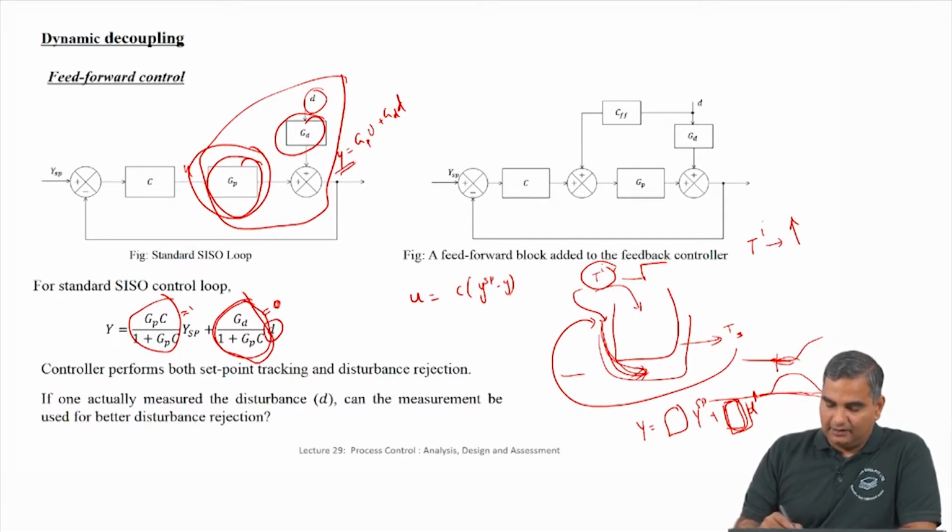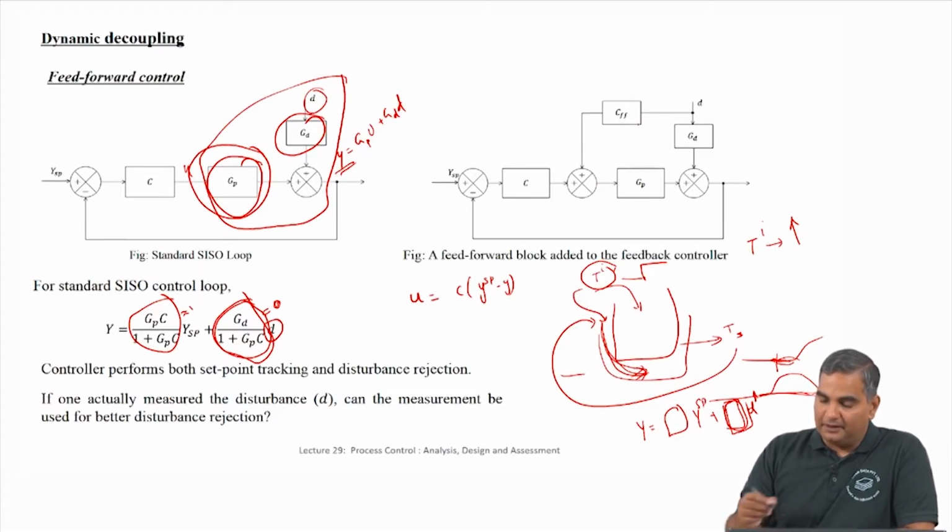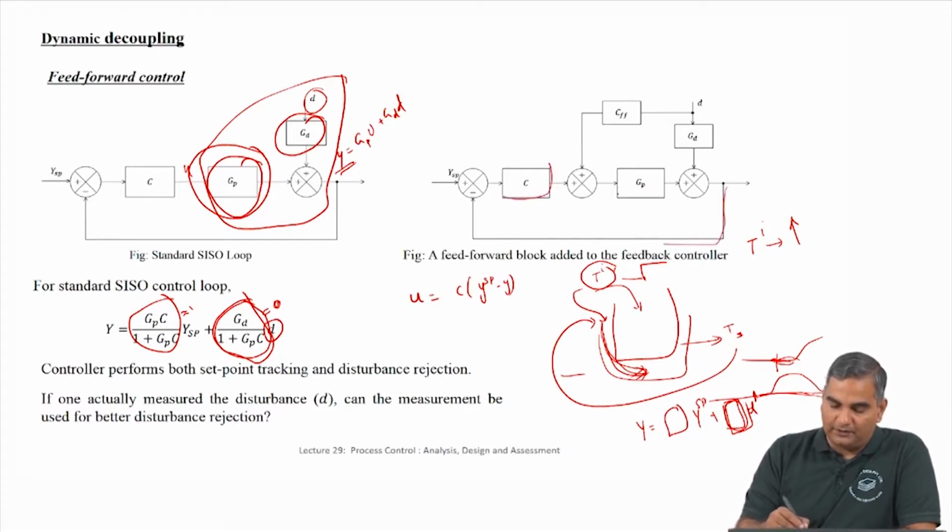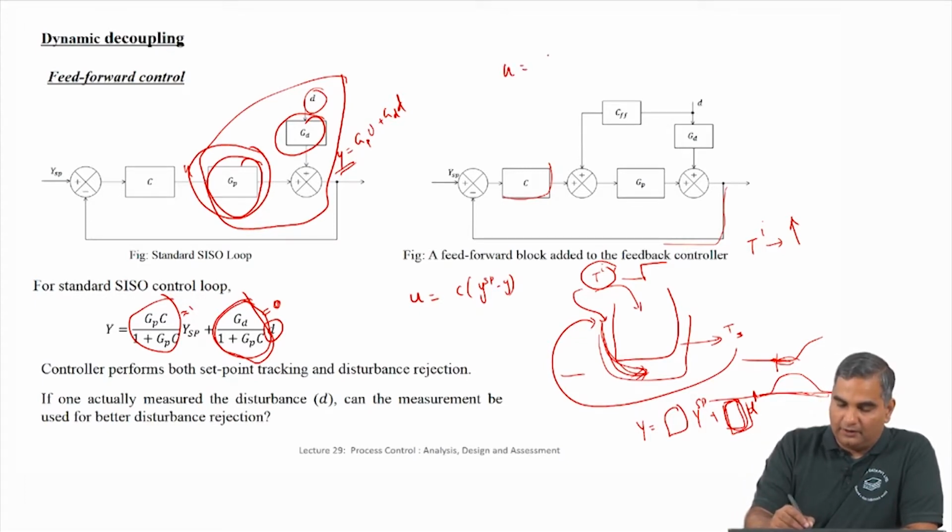So, if we take that approach, then basically here what did I say? I said the information about Ti has to go somehow to the controller, and the controller output has to be somehow modified. So, the way to realize this in the block diagram by adding more texture and layer to this diagram is the following. Typically, if you had only the feedback error, there is one block which manipulates the feedback error to give you some input, which is the flow. So, U is some control which is working on the error.